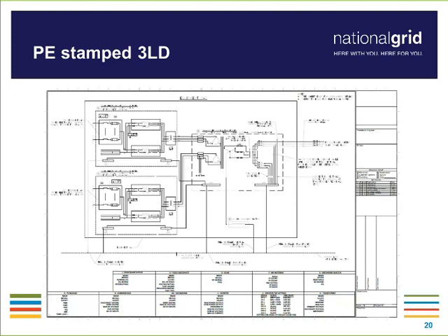So if you identify in a single line diagram that you have three of some element, and then come to find out later only one was installed in the field, and the only difference was maybe the three or the notation was overlooked or omitted, that can make a big difference in whether the project is a smoothly constructed project or if there's something we have to go back and have retrofitted or modified in the future, which of course would elongate the time from the process starting to the process energization.